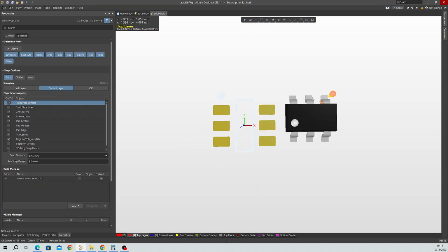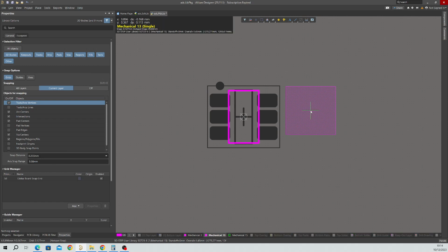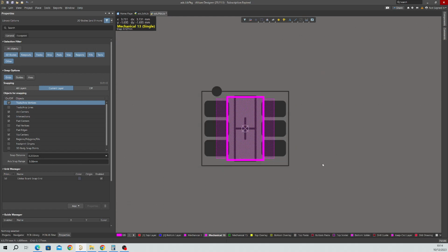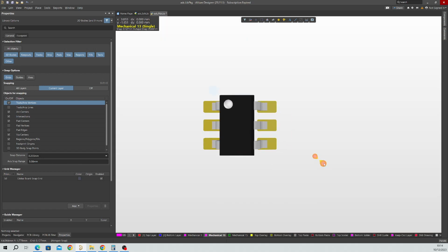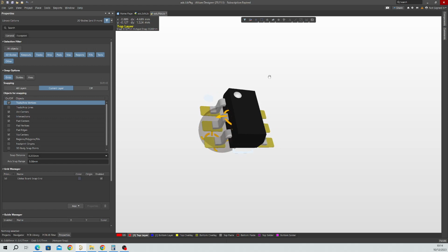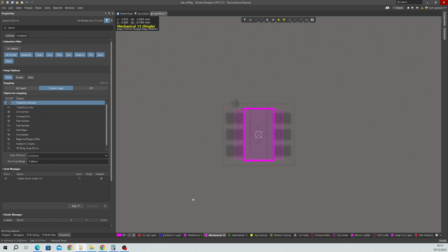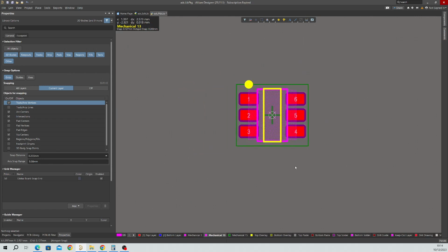Yes, it was 0. So I'm going to click on it, and then that's 3 times. Bring that and put it right over the edge. There you go. Making sure it's correct. Now that's a better model because now I can see a polarization. Okay. Pressing Shift S brings me out of single layer mode, and I get all the pad geometries.